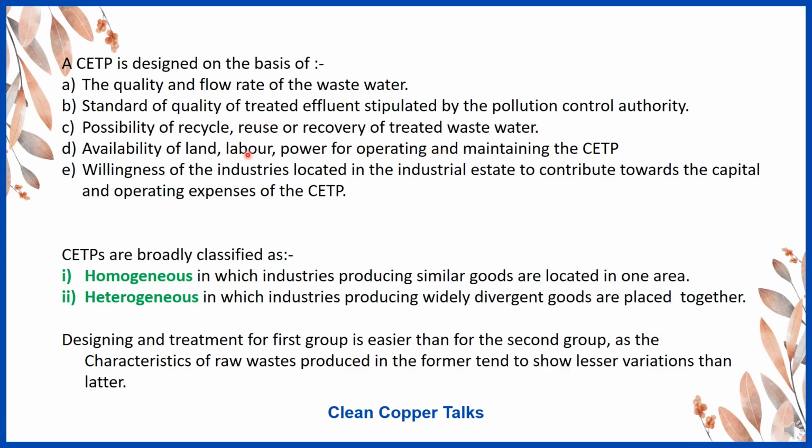Possibility of recycle, reuse or recovery of treated wastewater. Availability of land, labor, power for operating and maintaining the CETP, and willingness of industries located in the industrial estate to contribute towards the capital and operating expenses of the CETPs. These are all factors on which a CETP is designed.